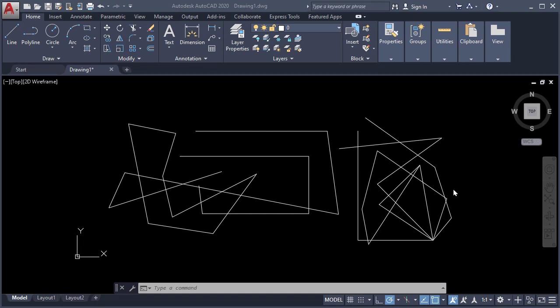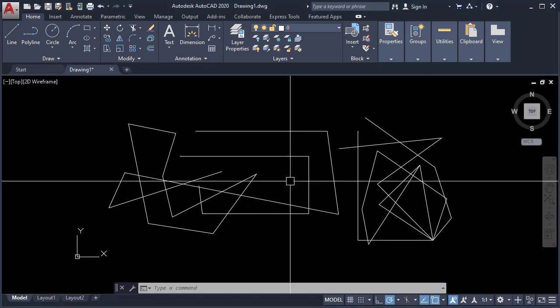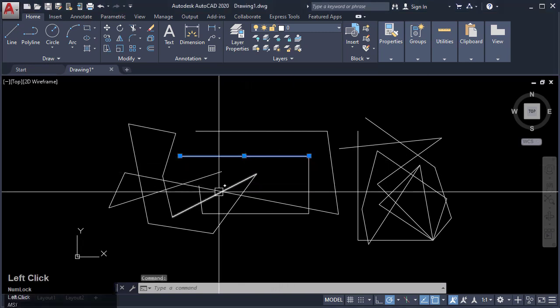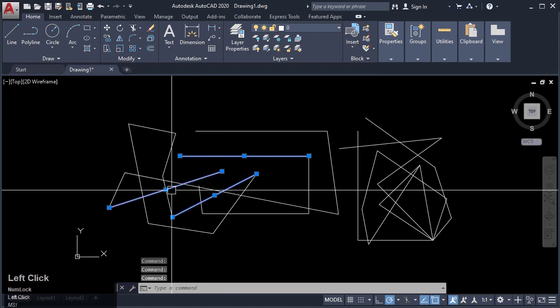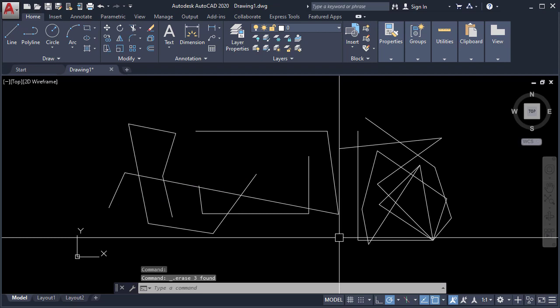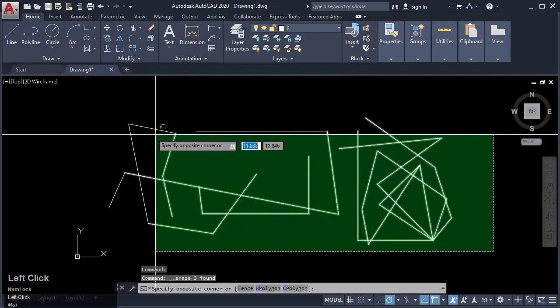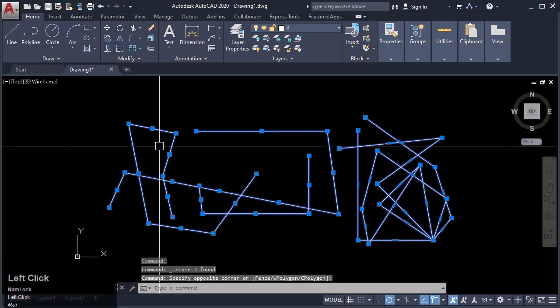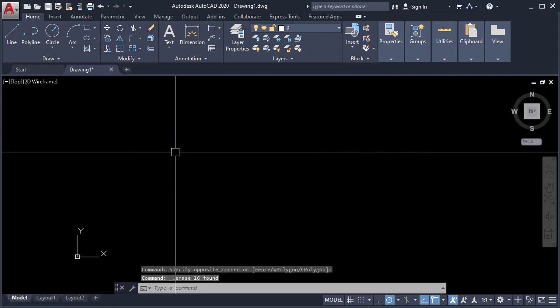For this portion of your activity, let's say you now want to delete certain items or lines in your AutoCAD drawing. So what you do is select those lines that you wish to delete, then simply press the Delete key. So let's now try to delete all of our items. Select all of those objects, then press your Delete key.